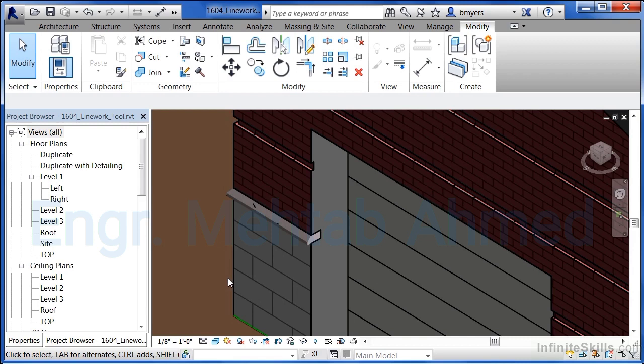So the line work tool can be used to punch out certain lines on the sides of buildings or remove lines that we don't need to see. It's great for documentation, and it's great for just tweaking individual lines, whether it be in section views, elevation views, or plan views, so that they display properly when it comes time to print out our documents.